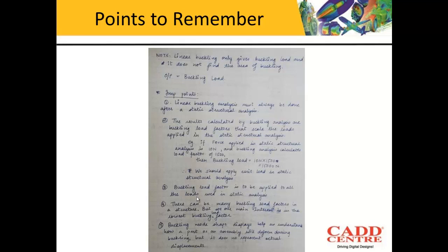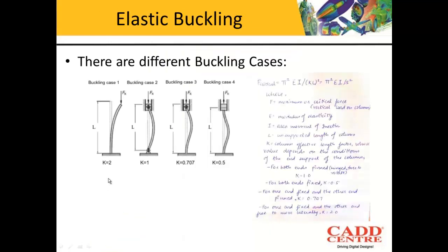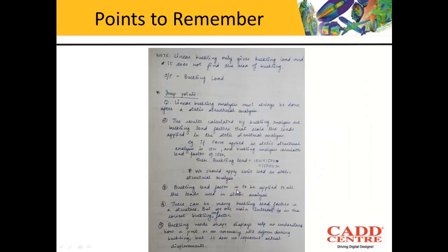The next point is the buckling load factor is to be applied to all the loads used in the static analysis. That means if there are two loads acting, if one load is acting from this direction and the other is in this direction, we will have to apply the load factor to all the loads that are applied in the static structural analysis.